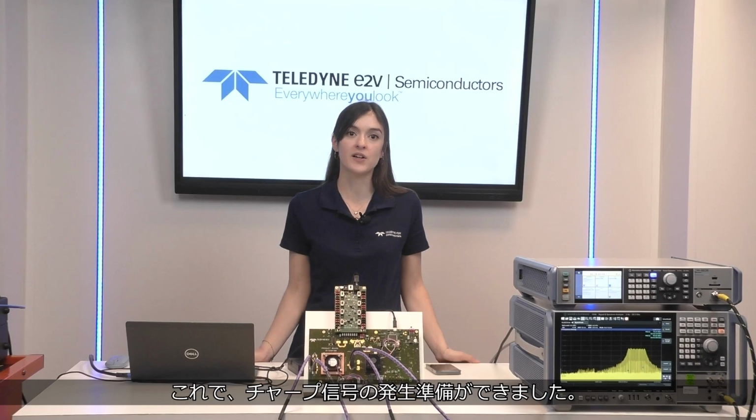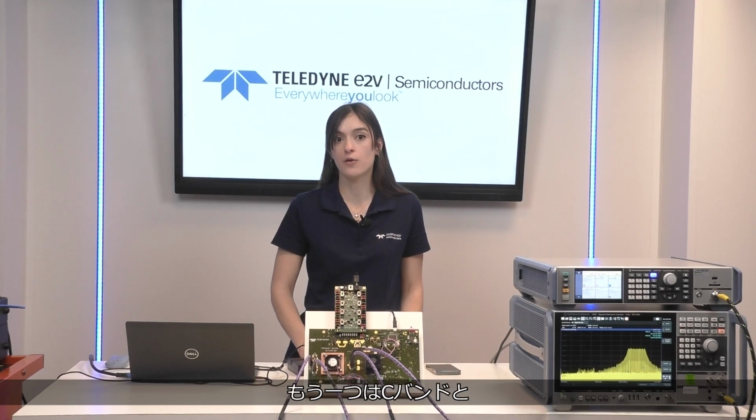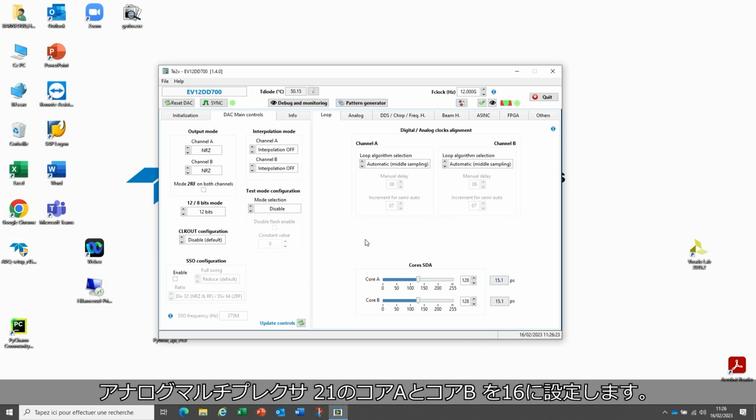Now we can start to configure the chirp. In this video, we will perform two configurations. The first one is the two DAC outputs in the X-band generating chirp, and the other one is one DAC output in C-band and one DAC output in X-band generating chirp. Here is the step-by-step configuration procedure. Set core analog mux 2, 1, core A and core B to 16.